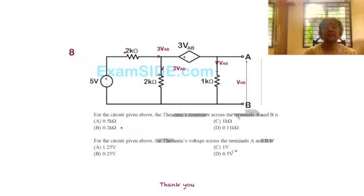Coming to the last problem in this section of DC circuits with dependent sources, let's have a look at the contents. As usual, we have the 3 VAB dependent voltage source, and it depends upon the terminal voltage, shown as A and B. These two terminals are where we consider the Thevenin's voltage as also the Norton's current if required.